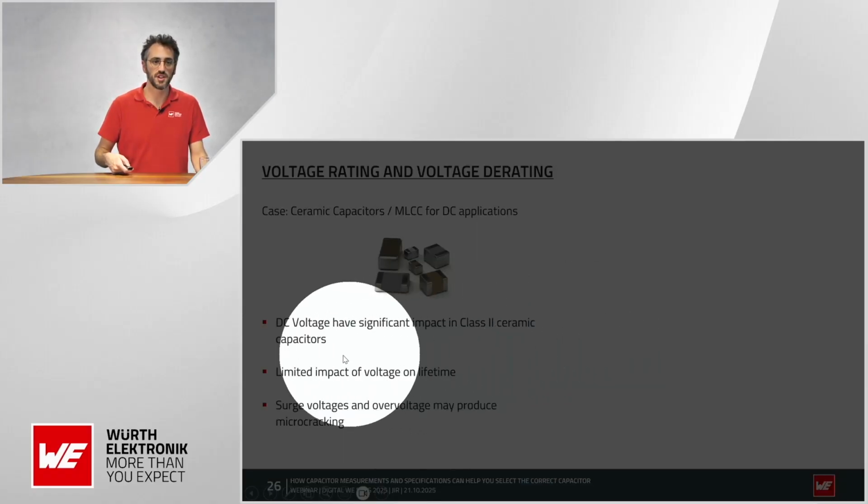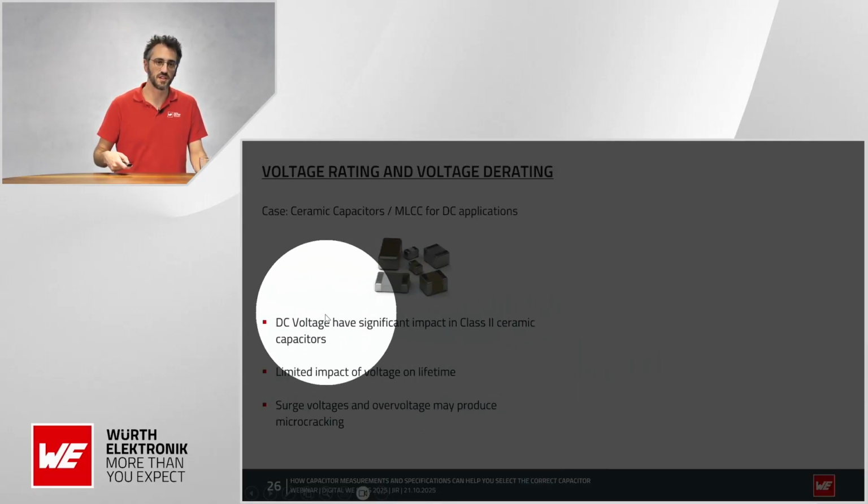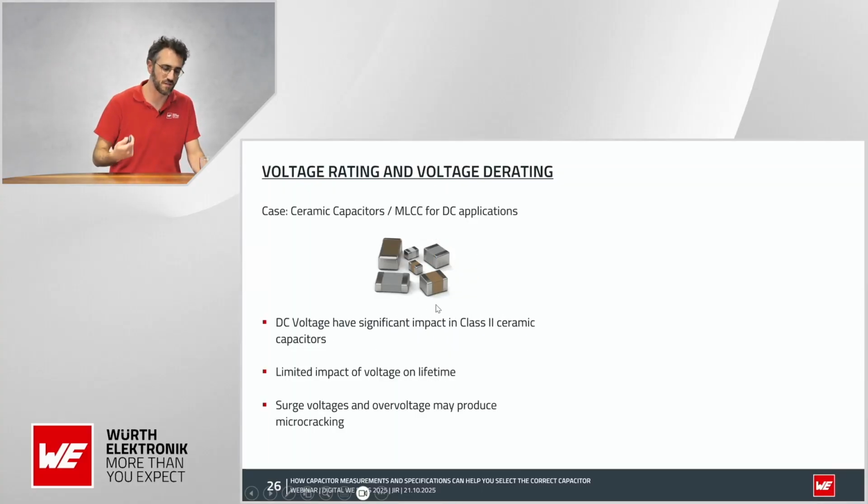Regarding MLCCs, the DC voltage has no impact on the lifetime, but as we have seen before, it has a huge impact in DC bias, specifically class 2 ceramic capacitors, so X7R, X5R, X6S, and this kind of capacitors.